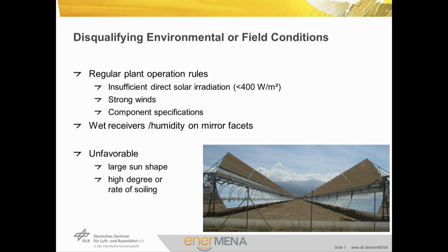There's a number of disqualifying environmental or field conditions if you want to ensure a good validity of measurements. As a general rule of thumb, assuring the representativeness of performance measurements, collector test conditions should agree with regular plant operation rules. This excludes periods of insufficient irradiation and strong winds. Wet receivers should be dried by focusing prior to testing to prevent undesired effects. Likewise, mirror facets that are wet due to dew, frost, or water from cleaning processes are critical. They should be dry and ice-free for testing.